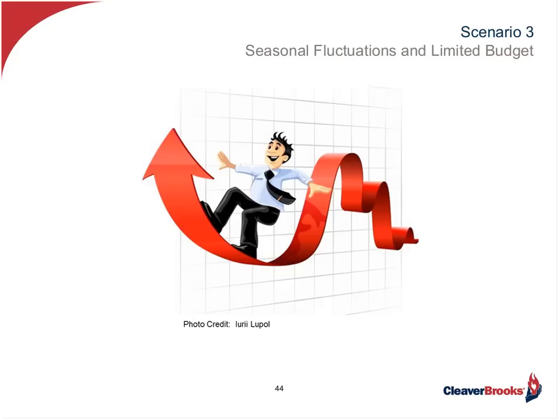Now, what about the seasonal fluctuations? As I mentioned in the opening, we have these situations where we've got one boiler or several boilers that are handling a process, but then in the summertime that process continues, but the heating load does not. This is often overlooked by engineers and people who are involved in the selection process. What happens to that load throughout the year? Does it change? And if it does, it can certainly drive your operational costs. They can become a killer because of the cycling that goes on in the summertime.